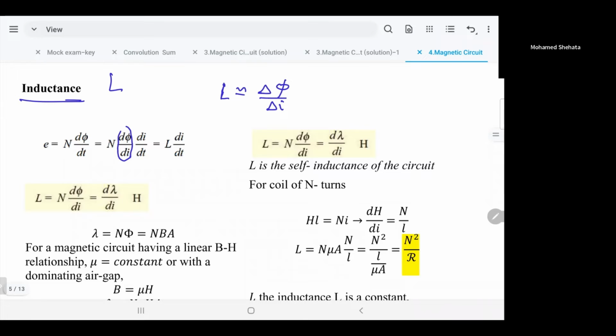All right. I just said, because of the negative sign, it means it's the reaction to the magnetic field. Now we are interested only in the magnitude. So that's the definition of the inductance. If we continue, L is equal to d phi by di, but actually if we have the N, we can put it inside to cover all the turns in the coil. So N d phi by di. So that's the definition of the inductance.